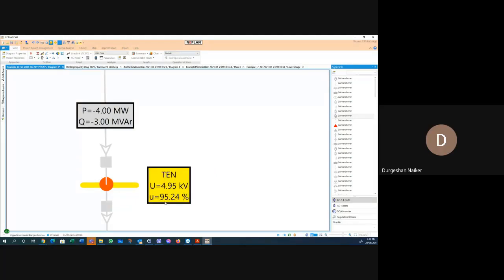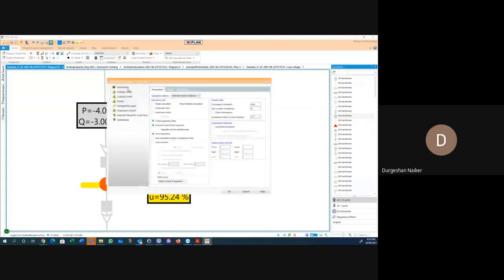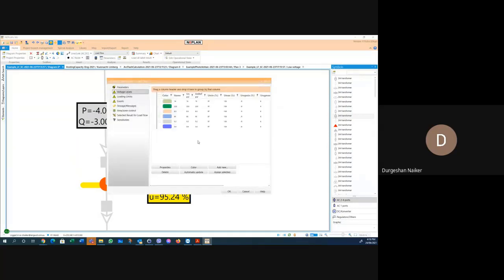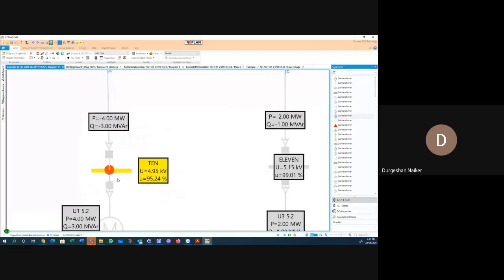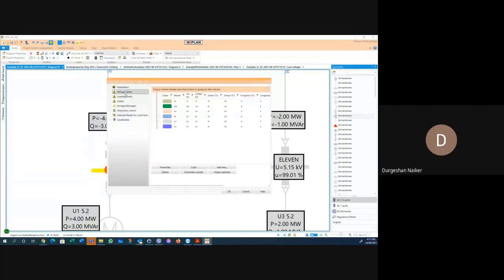What we can see is the voltage we are getting is 95. Remember, I showed you in the table that it is 97. Because it's below 97, it's complaining at node number 10. Now, just to show you, if I go back to my voltage level and go to, what is node 10? So this is actually 4.5 volts here. If I go here and change the setting,